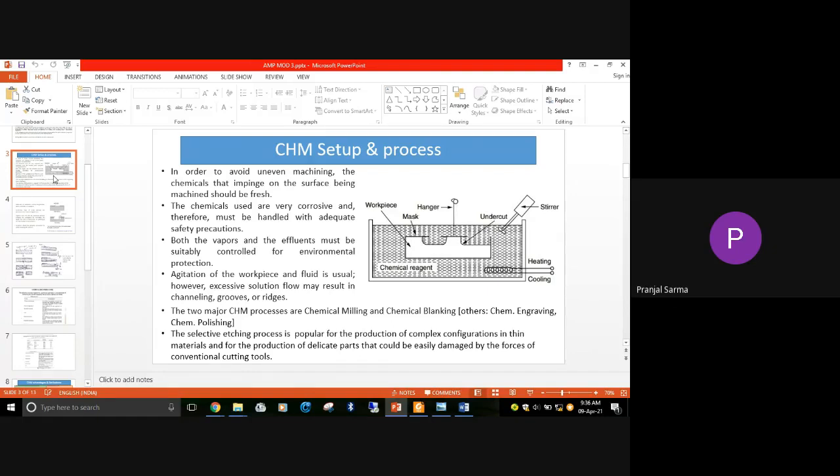Okay, sir. In layman's terms, you can consider it removal of material in chemical machining or that kind of chemical setup. That is nothing but the etching process. This material removal is etching. That's why we use the words depth of etch, meaning how much material has been removed or etched out.